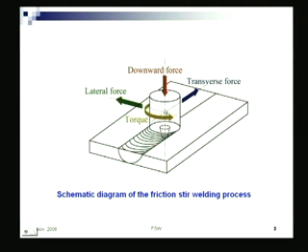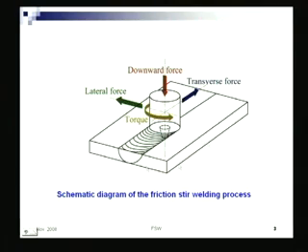because if it is made of a material having high thermal conductivity, it will have some performance. If it is made of a lower thermal conductivity, again it will have a very different performance, for the simple reason that, logically, this tool material should have much less thermal conductivity, otherwise a lot of heat will be wasted, dissipated.